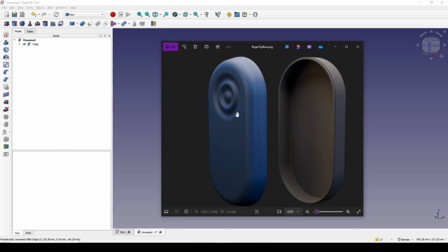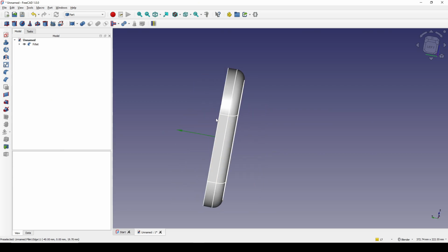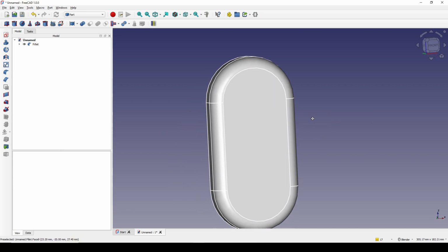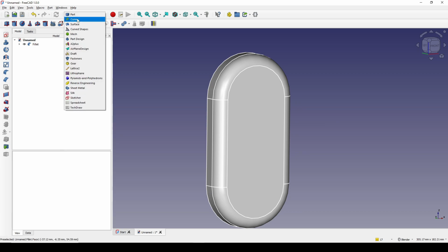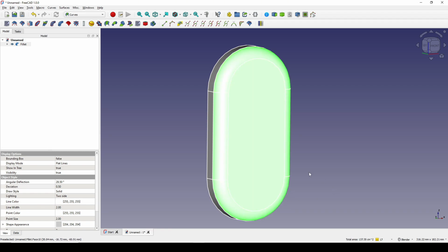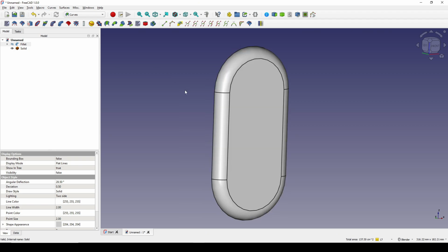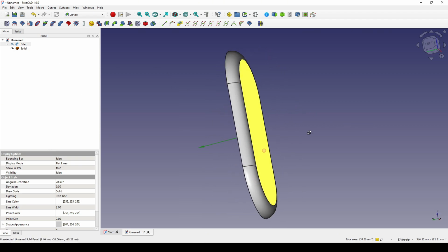And you can see in the picture, I want to create the front part of the lid. So I don't need these faces in the back. So I go to the Curve workbench and just simply control select all of these faces on the front. You can see these faces. And I click on the parametric solid to create a new surface. And I hit spacebar to hide the fillet, and you can see I only have this surface.